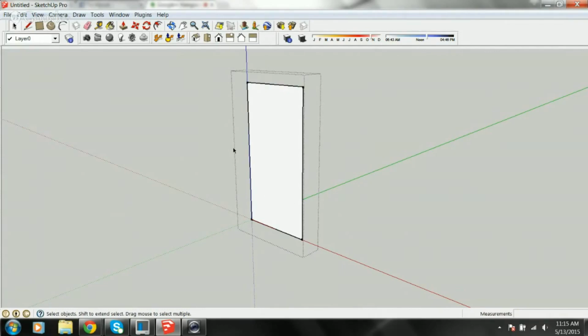Okay? So now I know the limitations of Shapeways in terms of the thinness of the material and how the details print. So there's no reason for me to create a 1 foot thick wall because I know that really doesn't translate to the thinnest material I can print in Shapeways and actually print successfully through their checks process. What I've kind of discovered is that between 1.5 inches and 3 inches is what you need to work with for a single plane. So for the sake of argument, we're just going to stick with 3 for today.